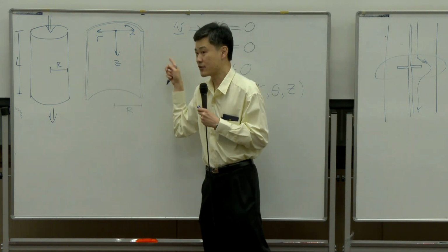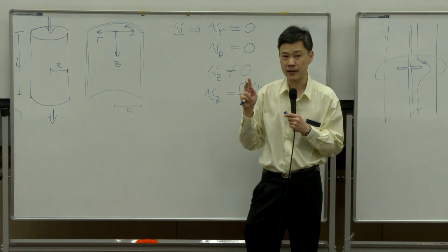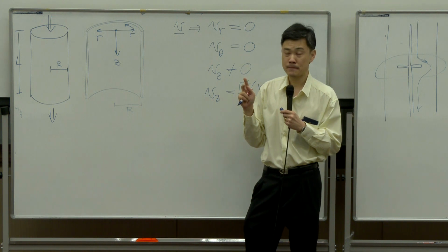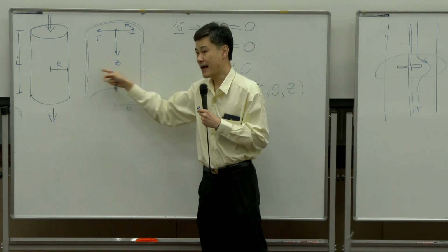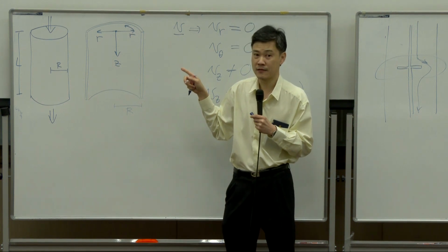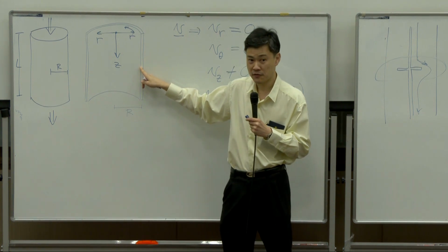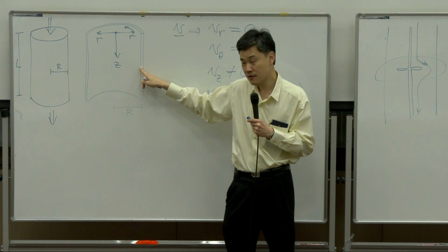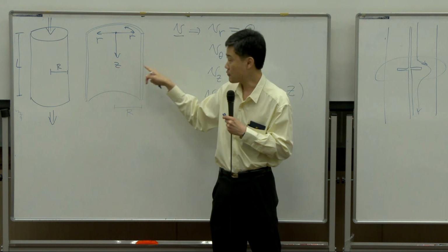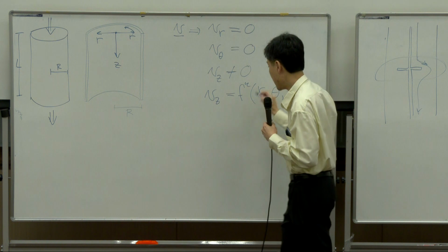Or in the r direction, can you find 2 points which have different velocity? Can you? In the r direction, at least there are 2 points with different velocity. At the wall, velocity is 0 under the no slip condition. Outside the wall, it is not 0. So right now, vz is changing with respect to r, right? So it is a function of r.